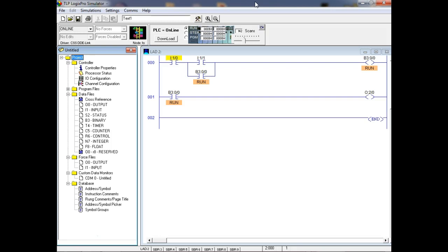Okay. Then use a switch to reset it. If the green push button and the red push button are each pressed 3 times, the red pilot light and green pilot light will turn on. The lights will stay on for 3 seconds. So that's both counters and timers. Everybody okay? So which one? Activity 3 from 9-3. Okay.